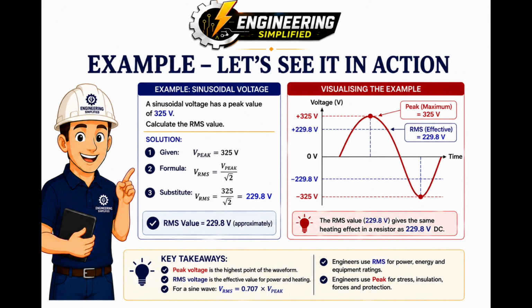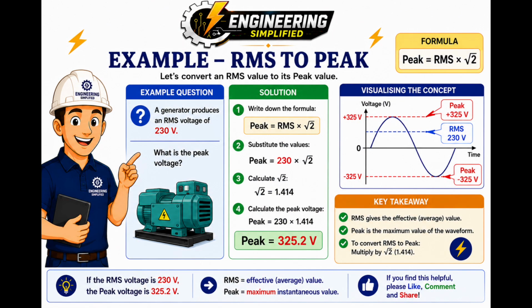And this explains something very important about a standard 230-volt AC supply. 230 volts is the RMS value. The actual instantaneous voltage rises to approximately positive 325 volts and falls to approximately negative 325 volts during each cycle. Now let's reverse the calculation. This time, a generator produces an RMS voltage of 230 volts. We want to calculate its peak voltage.